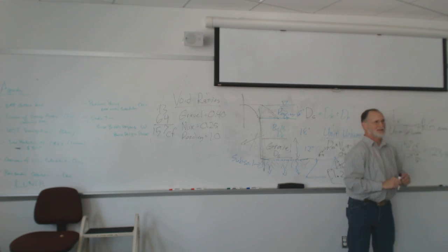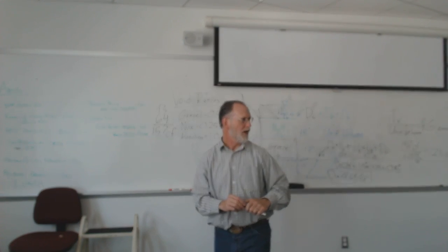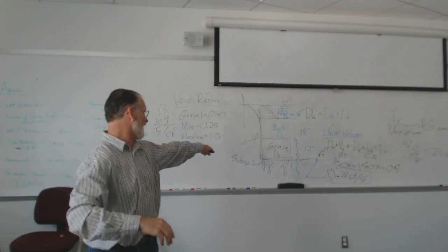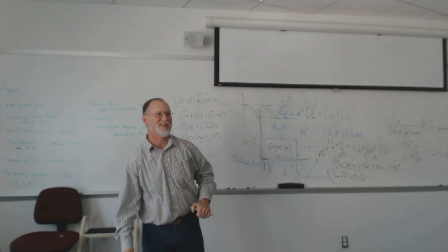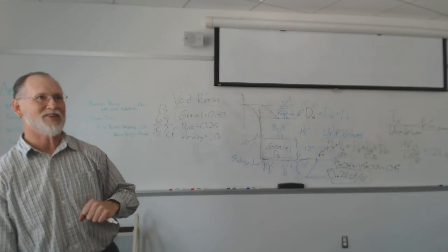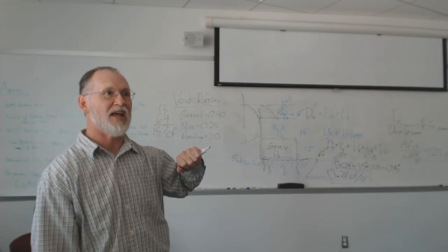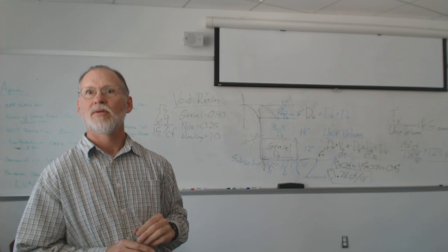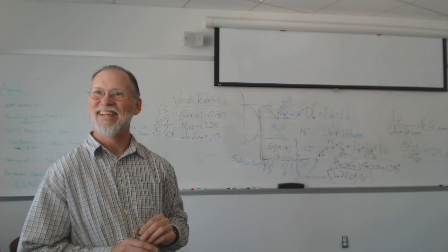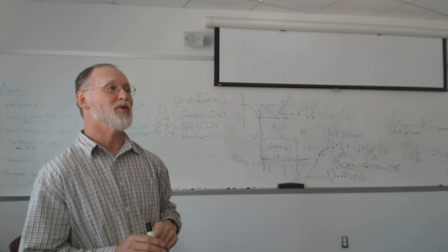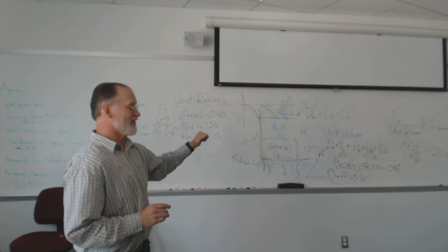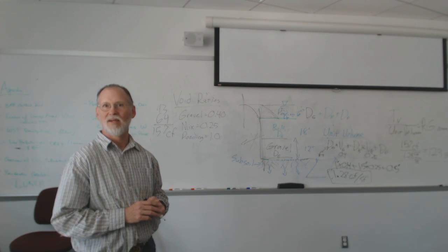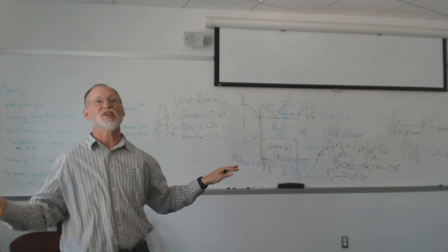I didn't measure that rain garden, and I don't remember. I think I had a lot more gravel than that under the rain garden. If it's too small, I made up the difference in gravel. But that's how you would size a rain garden at the very, very basics. Christine says the one on the right is 140 square feet. Bigger is always better. I think we still put in a lot more gravel and biomix, because I remember those holes were like 5.5 feet deep. I wanted a lot of holding volume because I couldn't put an under drain there.